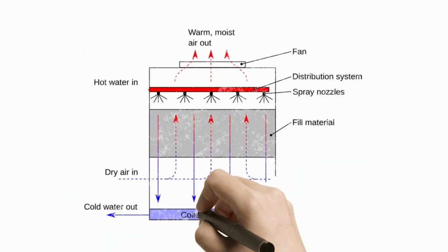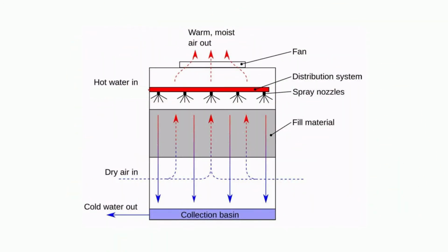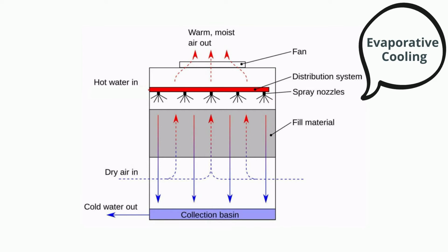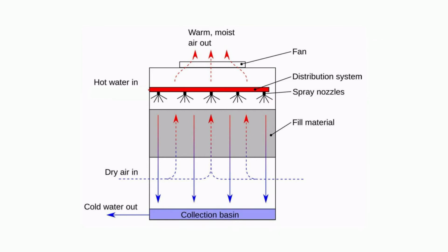Most cooling towers work based on the principle of evaporative cooling. Evaporative cooling is the process where warm water from an industrial process is pumped up to the top of the cooling tower where the water distribution system is. The water then gets distributed by cooling tower nozzles to the wet deck. At the same time, air is being drawn through the air inlet louvers, forcing water to evaporate. Evaporation causes the heat to be removed from the makeup water. The hot air naturally rises out of the tower.